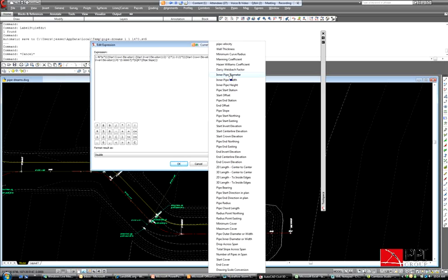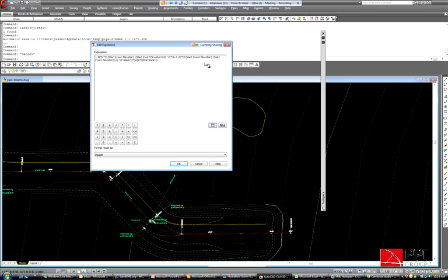There's a Manning's coefficient that, it'd be great if that worked, and I've escalated that up to my Autodesk guy, but the Manning coefficient doesn't work, and so it's in there manually, as you can see. But the way I was able to trick that out was I'm basically doing a start crown minus a start invert as my diameter in this Manning's expression.